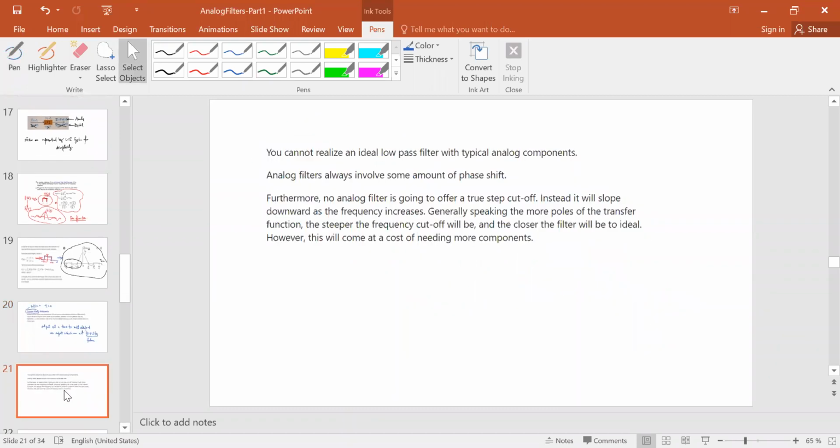There are other things that you cannot do because you have a sharp cutoff. You remember that in ideal filters, we have those sharp cutoffs in the frequency domain. You see this sharp cutoff? We cannot realize this sharp cutoff in omega. We can gradually taper it, but to realize this one, we need an infinite amount of memory when we are trying to do a hardware design of the filter. So these sharp transitions are not realizable.